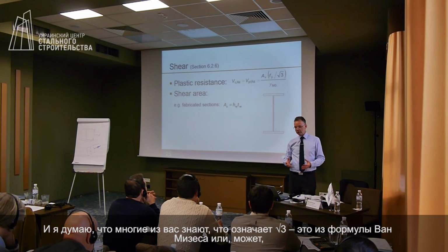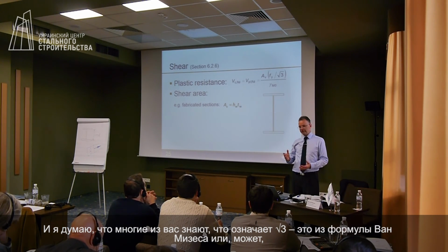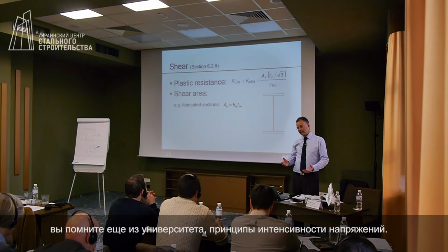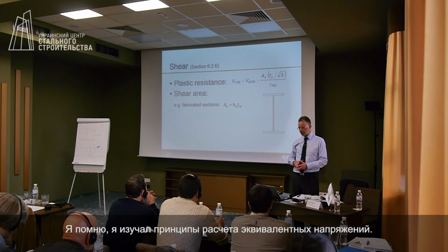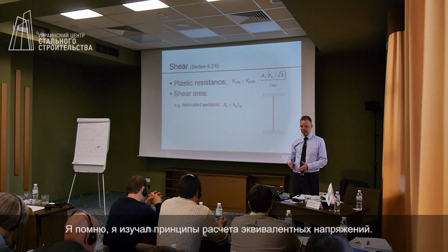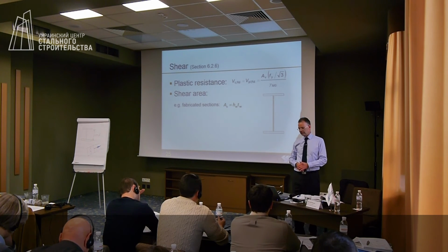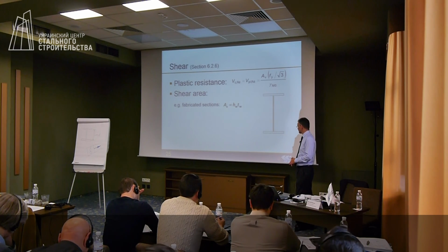And I think many people will recognise the √3 from the von Mises formula, or you may well remember from your college days, principal stresses. I learnt something called Mohr's stress circles. Okay, 1 or 2 people are nodding. And you will find √3 in those expressions.